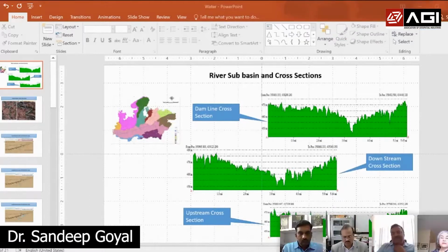This is one work we are doing with water supply schemes. For planning of water supply schemes, there is the Jal Jeevan Mission, JJM. We are working with our Public Health Engineering and MP Jal Nigam. They provide us the basic information on how much water they can get from the source, and then we do the planning based on the digital elevation model: where the intake well is, and where the water treatment plant should be constructed, so that there is the least pumping and more gravity flow. Then the MBR, main balancing reservoir, and the structures further on, the overhead tanks, and the design or route of the pipelines.